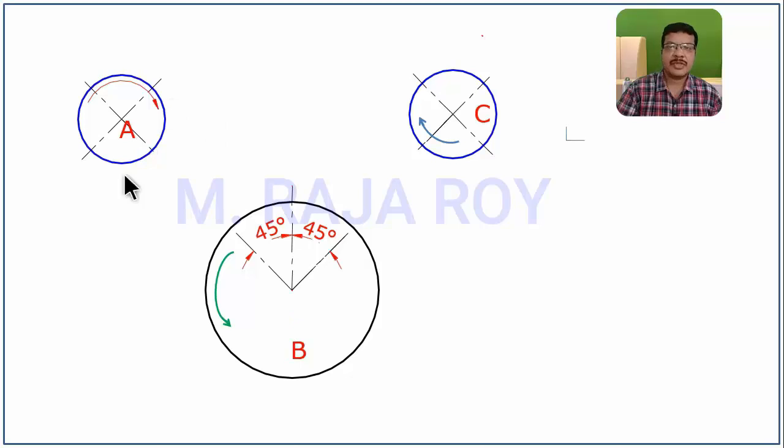Okay. Now draw the free body diagram. Separate all the gear wheels like this. This is rotating in the clockwise direction like this, means this gear wheel A will transmit power in this direction, in the downward direction, onto gear wheel B. That's why this will rotate like this. Power is transmitted from A to B, means the tangential component of gear teeth force is transferred from A to B. The tangential component of gear teeth force will be in this direction, that is downward direction, that will act like this on gear wheel B.